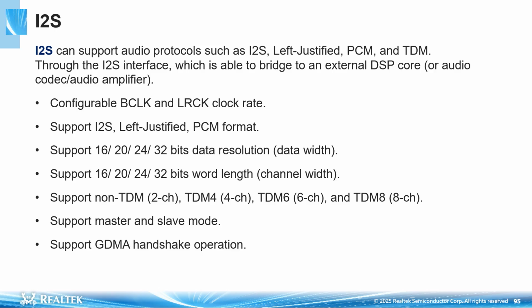Set the buffer size according to the amount of transferred data in GDMA mode, or access the I2S FIFO directly to transmit and receive data in FIFO mode. It is recommended to transfer the audio data via GDMA automatically since it can reduce the number of interrupts and improve efficiency.